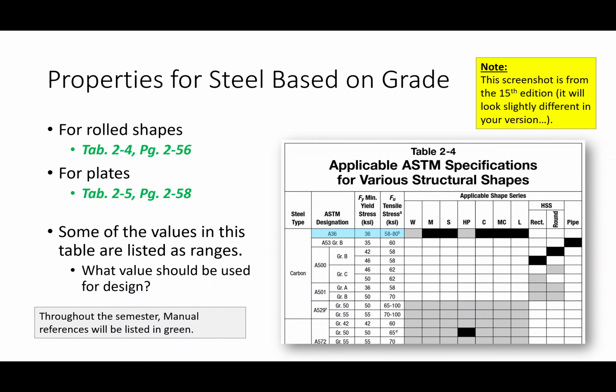And basically the reason is that if you take a piece of angle and go test it in a tensile machine, you'll find that its yield stress and tensile stress were well above these values anyways. It just took a while for standards and whatnot to certify them as exhibiting those loads.